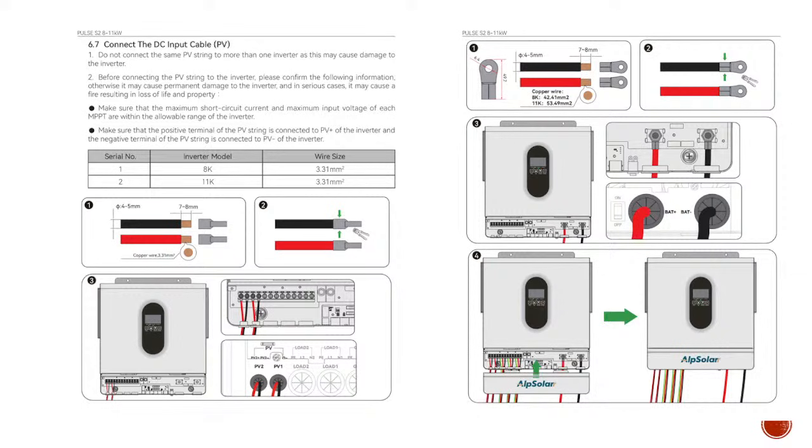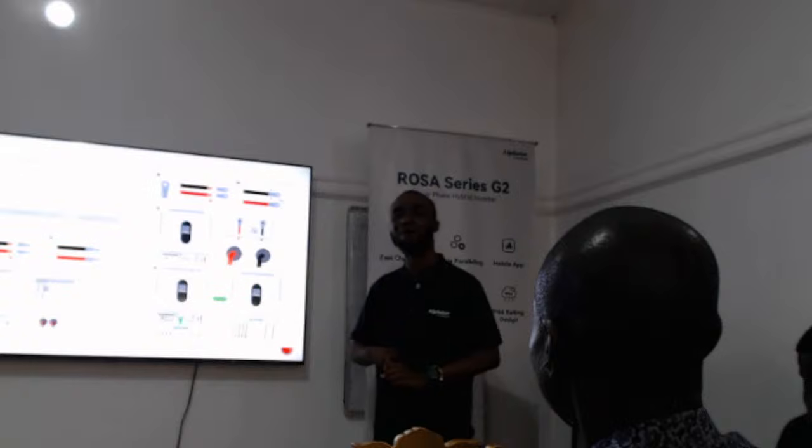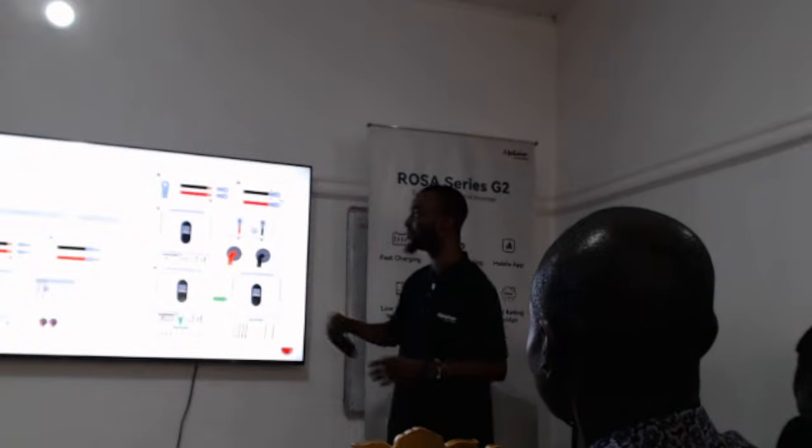Yes, one battery bank. The first time I saw it, it shocked me, and they came up with one excuse: just one of them is charging the battery. Just one battery bank. See, they paralleled that same battery to serve 3 different inverters. That might be pardonable, but don't try that with PV.